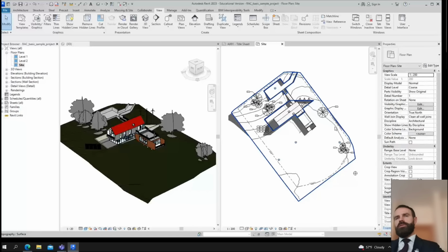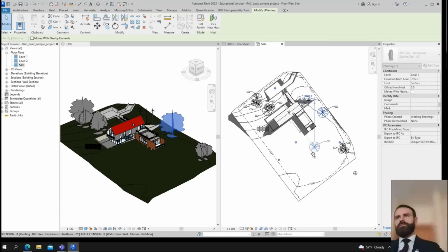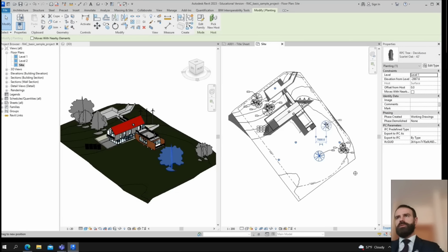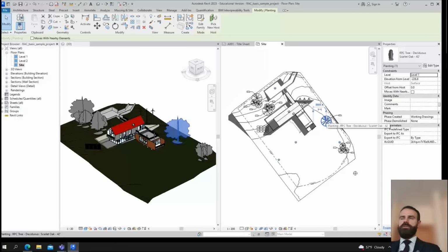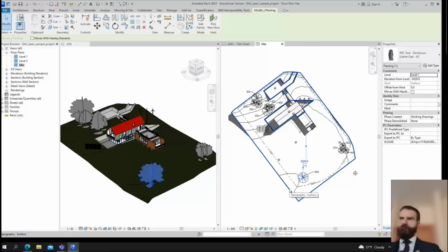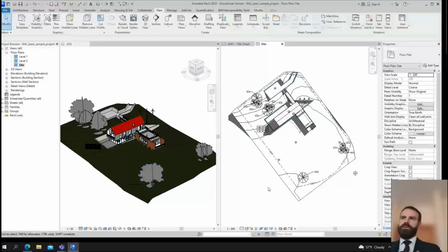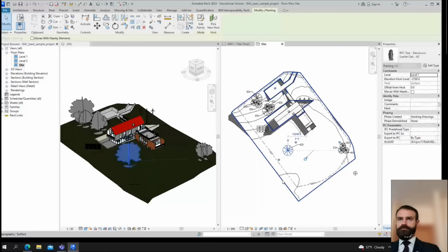So in a Revit model, all things are related, linked. And if you modify an object in one location, it automatically modifies in all your views, all your settings. So this is also the difference with AutoCAD. In AutoCAD, if you change one object, it just changes this object and it doesn't change other views or drawings. Of course, depending on how the AutoCAD drawing is created.